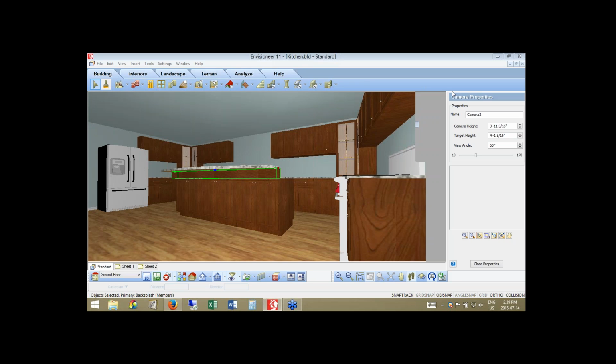This pantry unit, just like I modified the look of our dishwasher cabinet, I can do the same here. I can say it's type 1, remove the door, so it's just a box unit. Go to that details page. Again, it'll have to have something of value in here, so you can type in a width and a depth, but it will have to put some kind of bottom on it. But you get that box. And then from there, you can put your refrigerator in there.